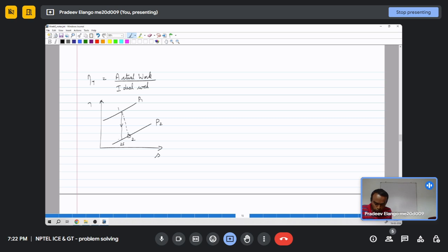Right? So if you have gone isentropically, we will have H1, the enthalpy change is delta H, or work output is Cp into T, or okay, I will write this enthalpy 1 minus enthalpy 2s, or this is Cp into T1 minus T2s.